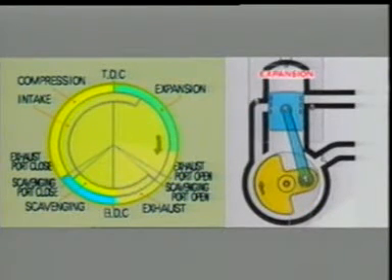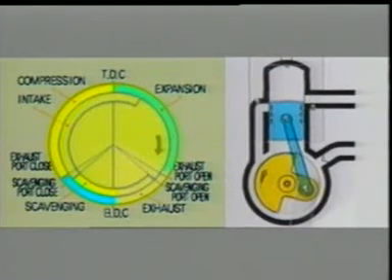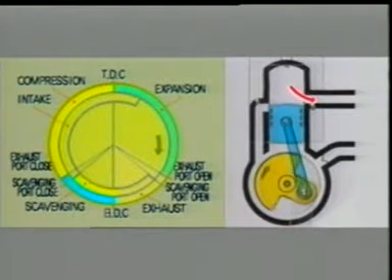When the piston is pushed down by combustion, the mixture in the crankcase chamber undergoes primary compression. As the piston descends further and the exhaust port in the upper chamber of the cylinder opens, exhaust gases are propelled through the port by virtue of their own expansion pressure.